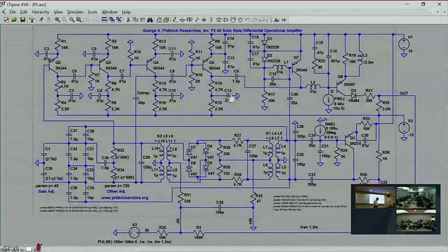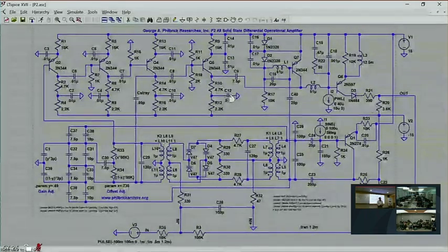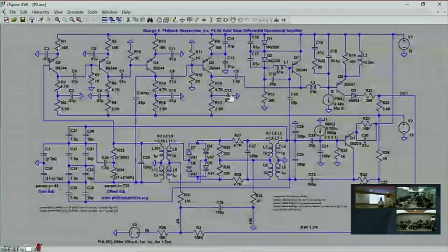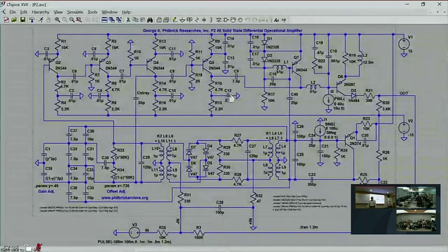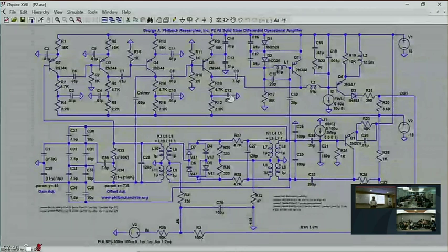Now, George A. Philbrick created the op-amp market. I mean, the very idea that a commercially viable product would be an electronic amplifier that had so much gain, it was useless. I mean, an amplifier that would amplify its own offset voltage so that the output was just stuck at one rail or the other, that's a product that people will pay for. That idea is due to George A. Philbrick. He says, well, people put a resistive divider around this thing to program the gain with feedback.